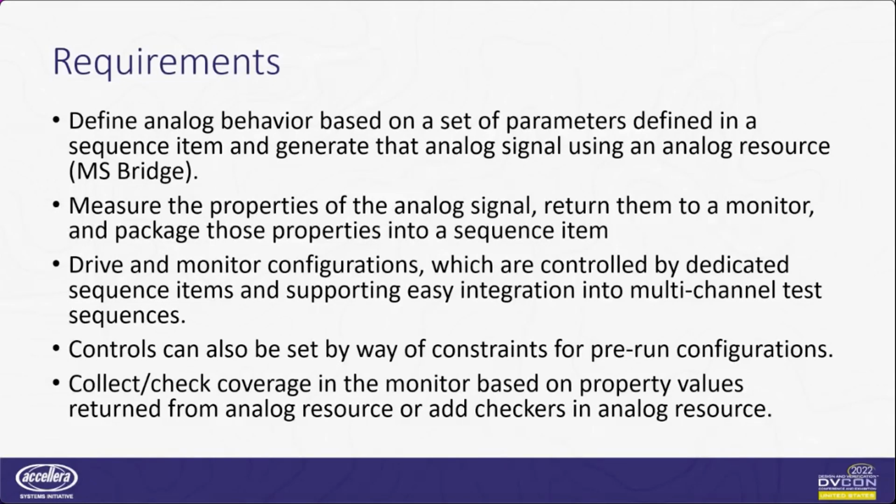So this will allow us then to define these controls and set them using constraints for pre-run configuration. So we can rely on the SystemVerilog constraint solver to choose the values that will then be applied to our analog test bench to make these different interesting configurations happen.